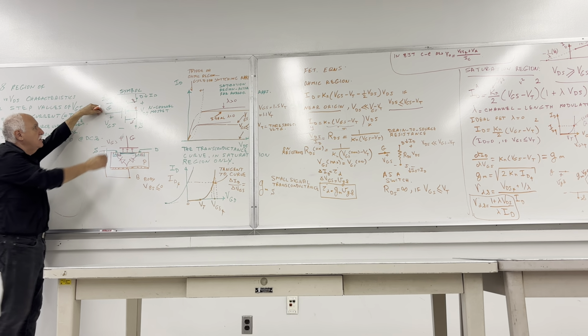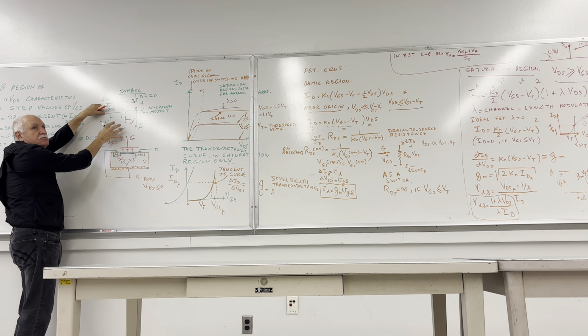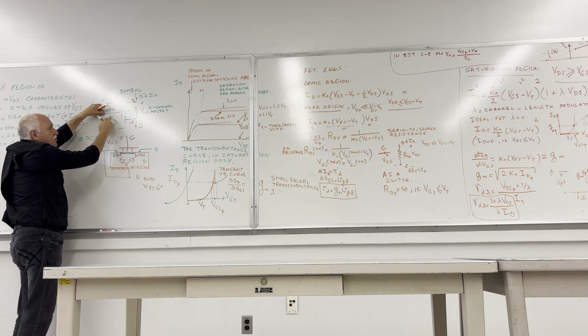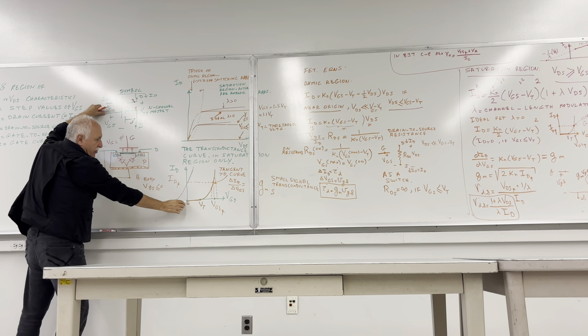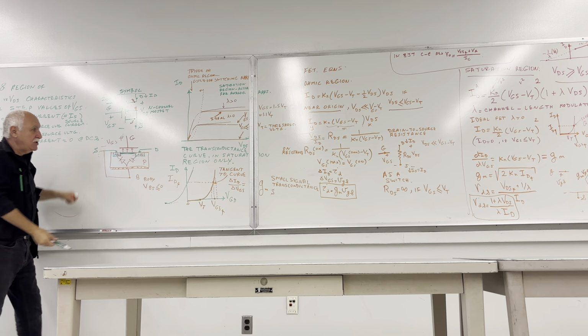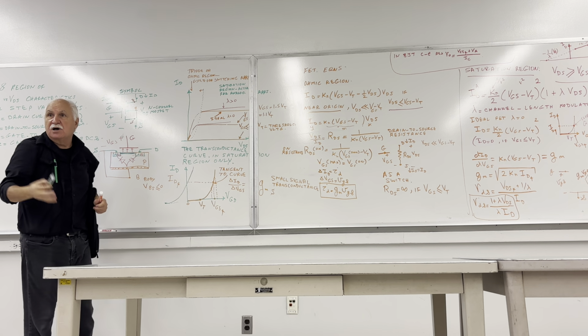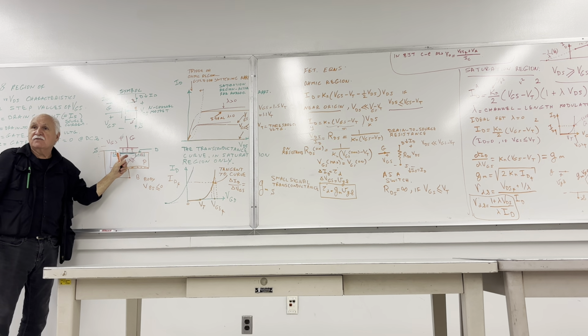All you have to do, just put the AC source from here to here, straight. No biasing necessary. If you put AC source from here to here, your VGS DC will be 0. That means you will be operating in here, up, down. That will give you actually a maximum gm in here. Quite a maximum slope, which means gain. The higher gm, the more is the gain. So those are perfect for analog communication devices.